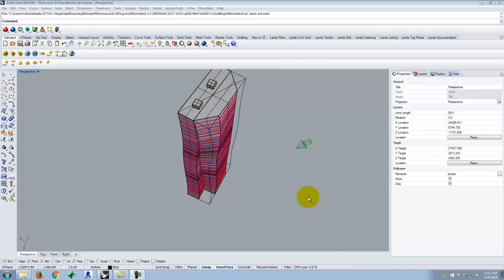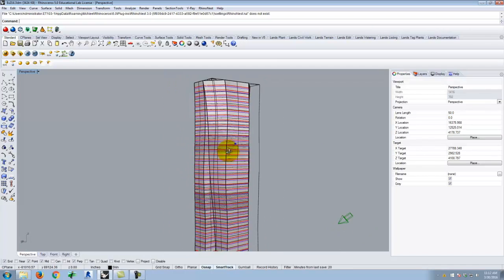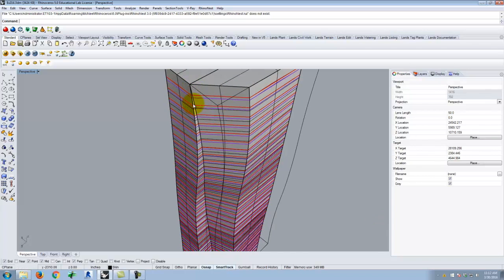The truth is that for this operation to work, we need to have ruled surfaces, so we can't have bulging in two directions or two-dimensional curvature. I.e. like a sphere or that kind of a bulge where we have curves in both directions. The skyscraper that I did, if you guys remember back to that, does have plenty of curvature to it, but it's curvature always in just one direction. So there's always a straight line that goes across.